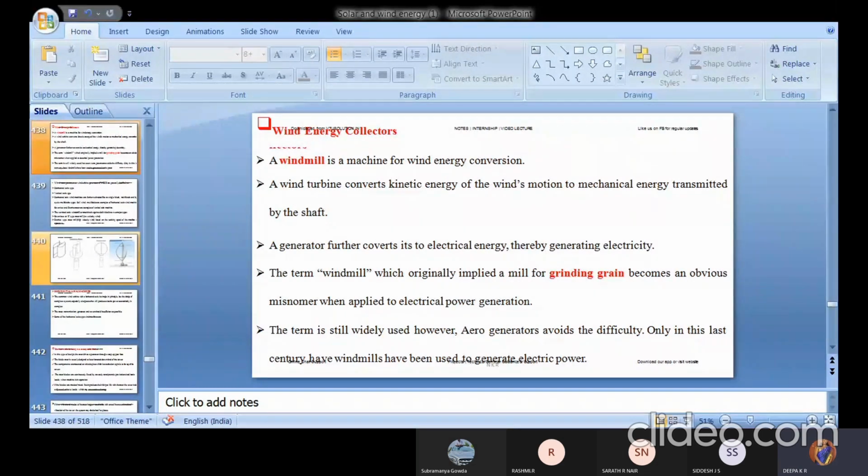So the system is mechanically designed to hold for a given speed. Some speed is fixed; for this speed, nothing will happen, the system stays in healthy condition. If it goes more than that, or the system runs continuously for a longer period, then vibration will definitely happen. So the vibration mode of the rotor will coincide with one of the natural modes of the tower, and the system may shake by itself because of the high speed. It is not possible to hold it.